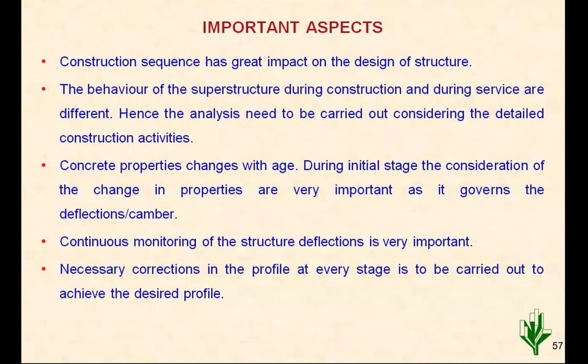Then we check the actual concrete strength and value of elasticity of concrete achieved vis-a-vis what we have considered in the analysis. That is the first check. Then the second check is about the density of concrete. Then the third check is the forces applied on the cable, that is the pre-stressing force applied on the cable. If those are similar to whatever we have assumed in the analysis, that can be monitored.